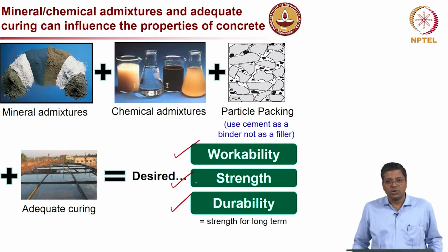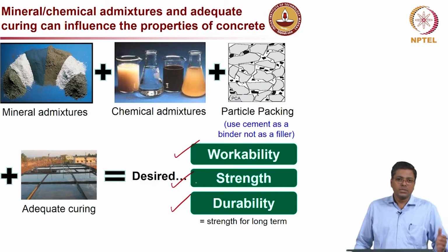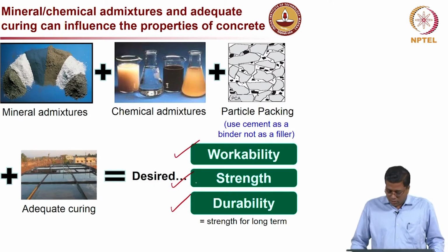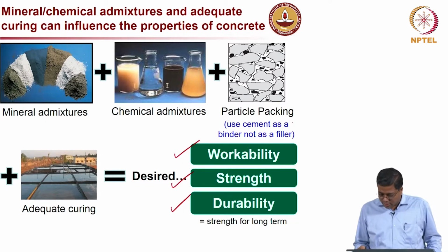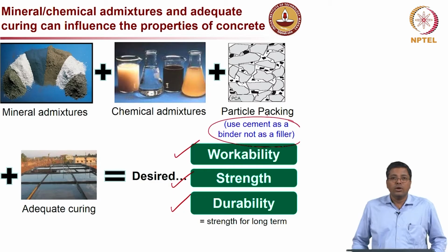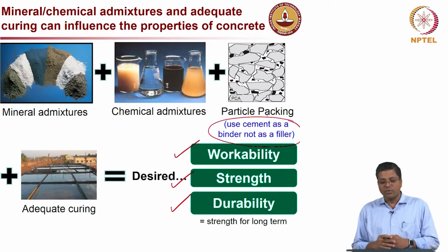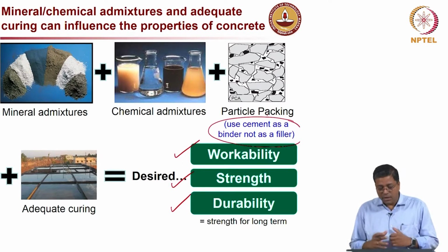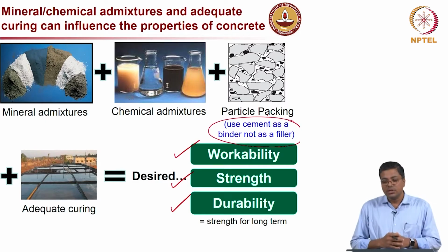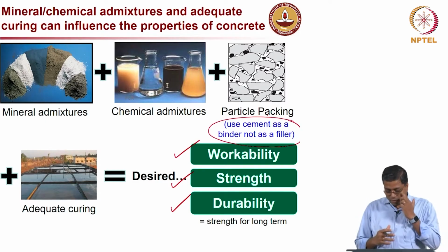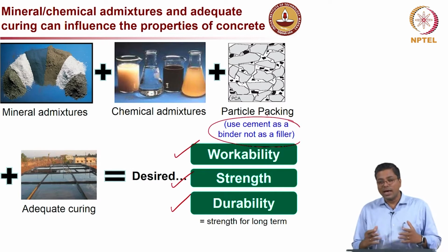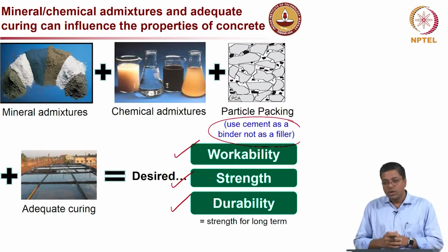And essentially what is durability? It is nothing but strength in the long term. So, one thing to mention here was that the use of cement should be considered not as a filler, but as a binder. In other words, when we talk about mix design, we should think about having a minimal amount of cement, which will play a role mainly as a binder or a glue to hold all the aggregate particles together.